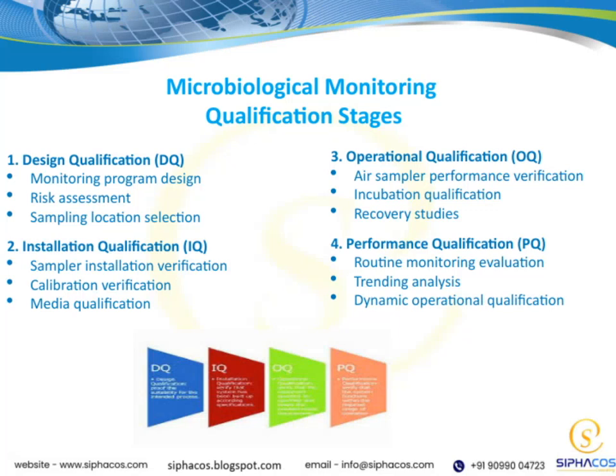Now, let's walk through the key stages of microbiological monitoring qualification. First, we have design qualification. This is where we plan the monitoring program, assess risks, and choose sampling locations. Next comes installation qualification, which ensures samplers are installed correctly, calibrated, and that the media used is suitable.